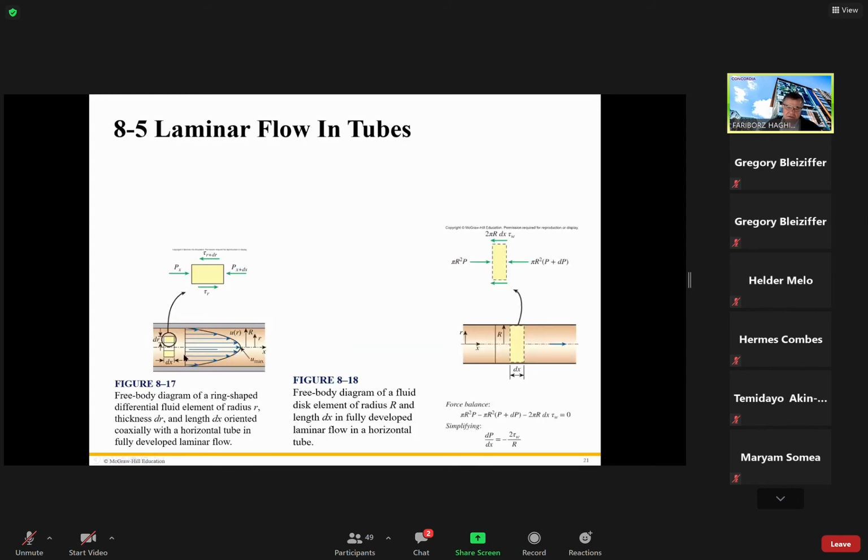Now, how can I calculate the heat transfer coefficient? Look at here. You remember this one, the velocity boundary layer, the velocity profile. This is the pipe, the fluid is passing through it. I take a control volume. Again, this is a small cylinder of thickness dx, and again it is a control volume. This is radius r, and this is r plus dr.